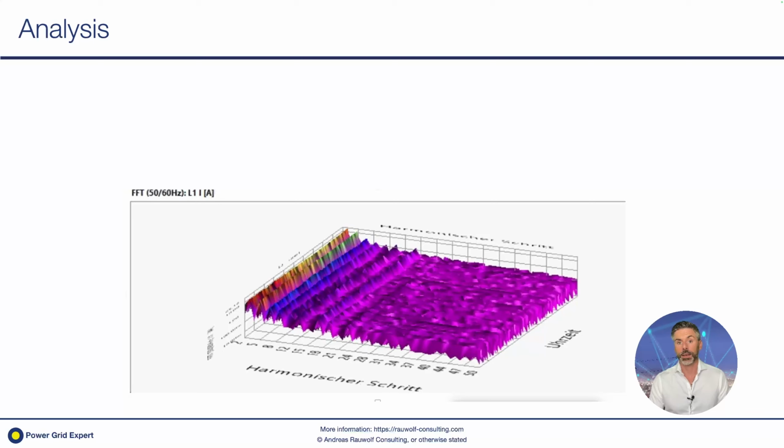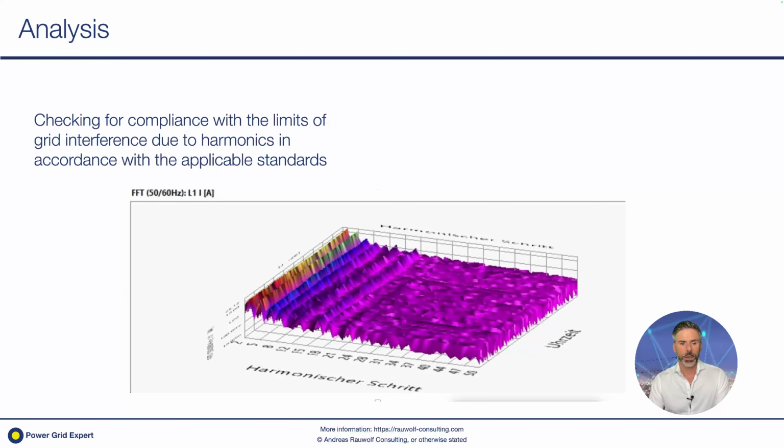If I go to the analysis of my measurement, then of course I have to check for compliance with given standards for grid interference, talking about harmonic distortions.